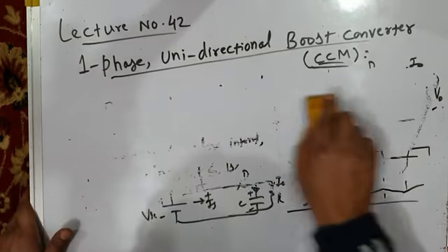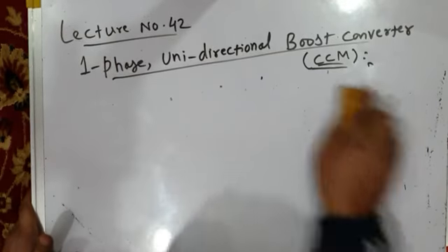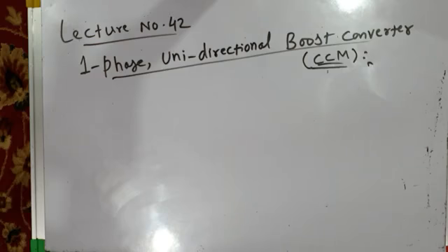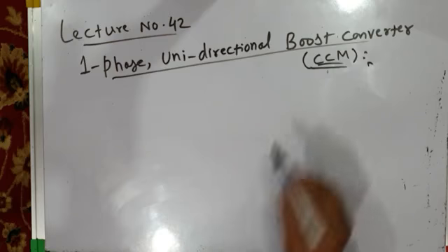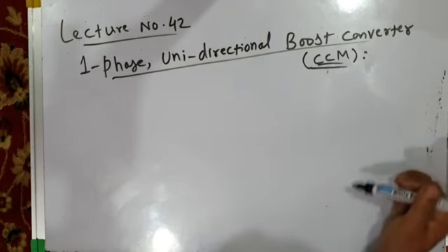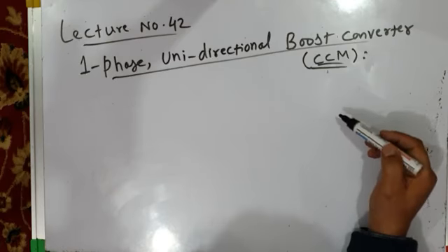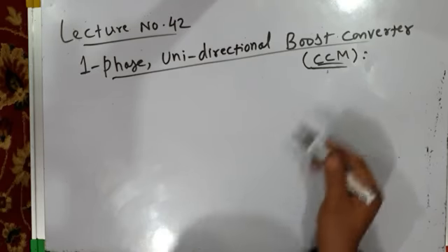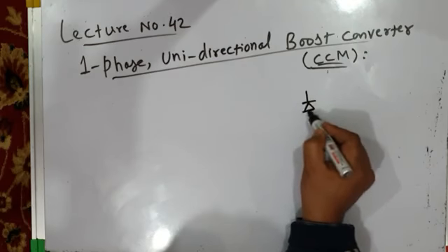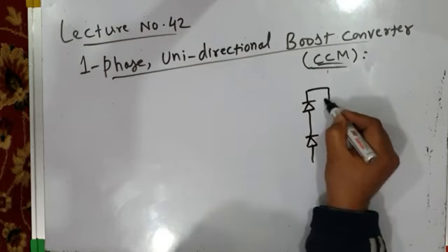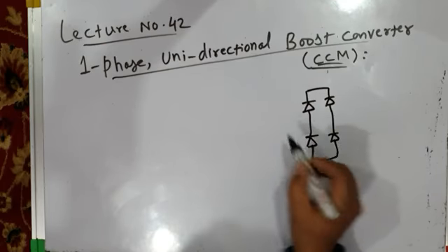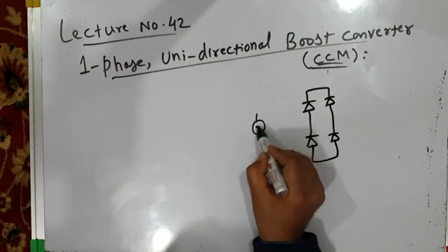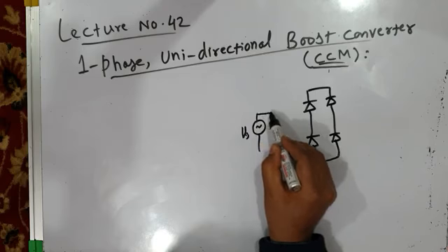Now in our case, our converter is not a DC to DC boost converter, it is an AC to DC boost converter, now operating in continuous conduction mode of operation. When I say it is an AC to DC boost converter, it actually comprises a DC to DC boost converter which is connected to rectified AC. That means on the AC side you have a bridge rectifier, a diode bridge rectifier like this, which is a front end rectifier. And this is the source voltage,